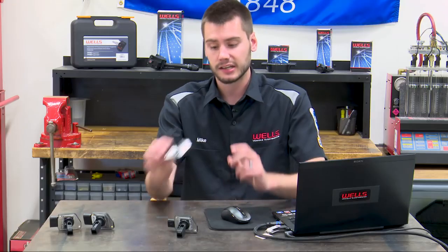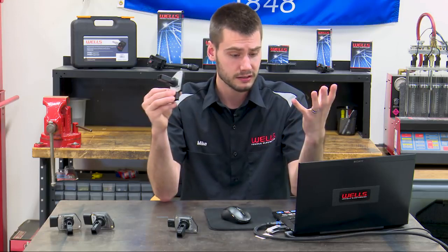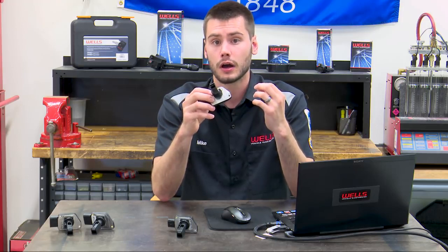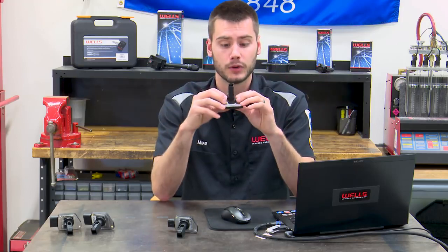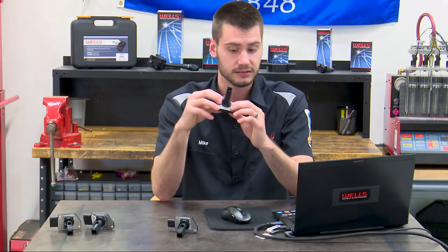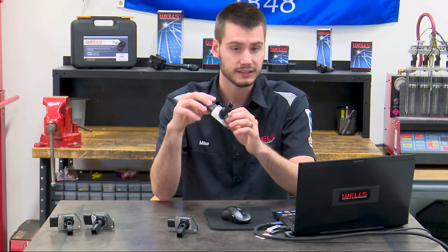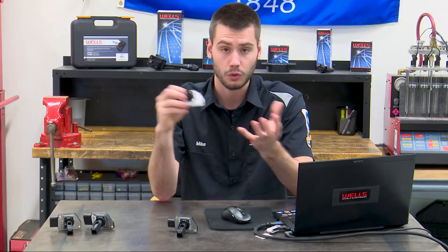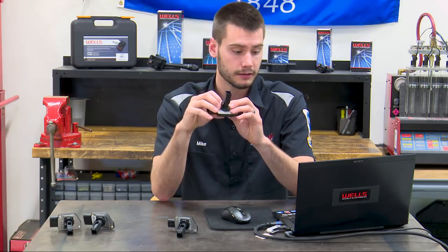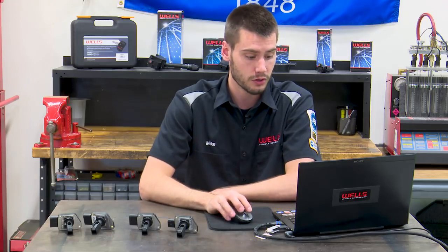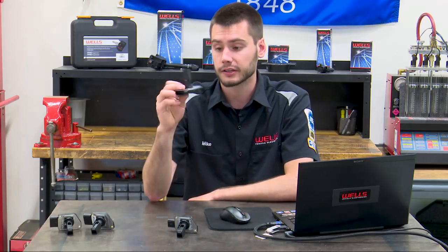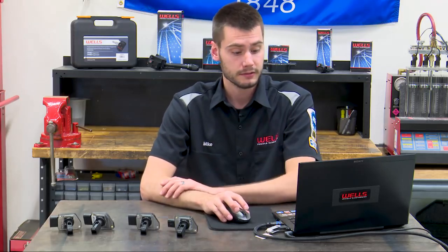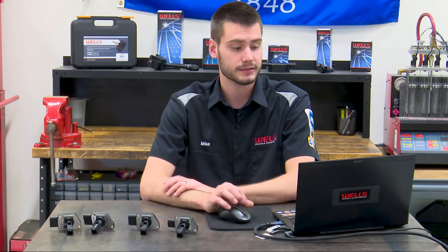So does cleaning our sensor with cleaner really take care of the problem? Is it really cleaning anything? Is it really bringing our sensor back to new operation, back to fully functional operation? I would say no. I would say this sensor is still not where it should be. I don't think this sensor could ever be 100% again. Our coating is no longer intact. The sensor will fail and will fail more frequently than it did before. So I don't think using mass airflow cleaner on our sensor here took care of it. So in my opinion, the best way to do this would be to replace the sensor.